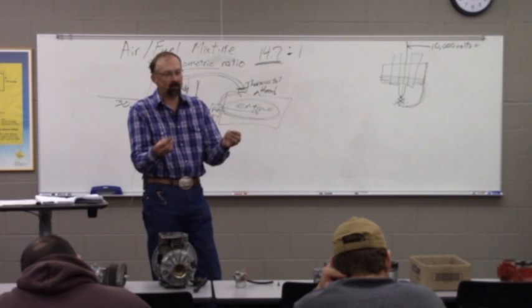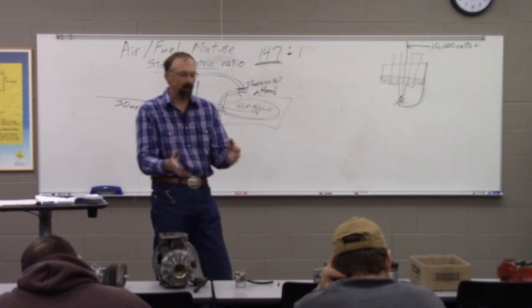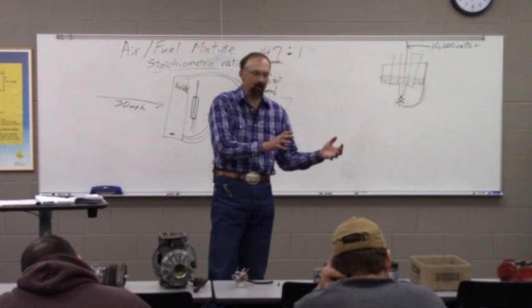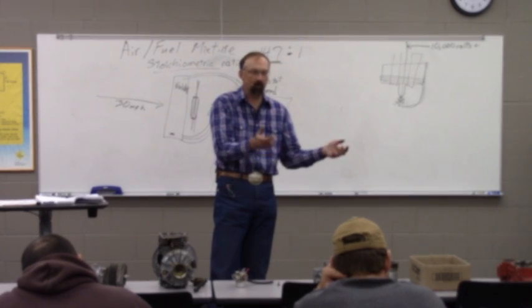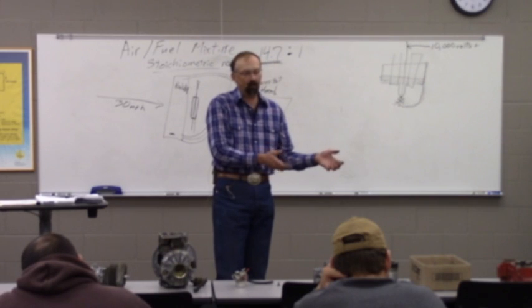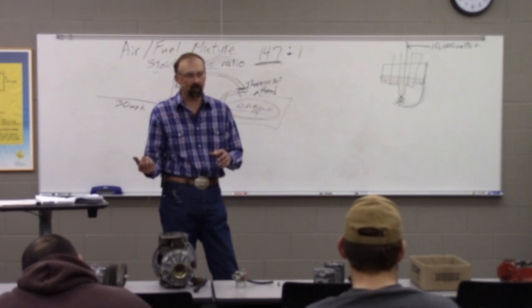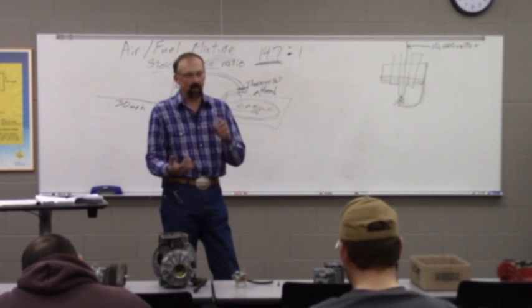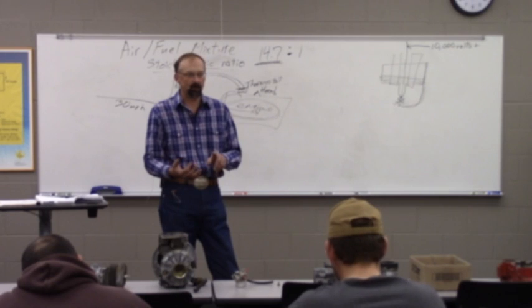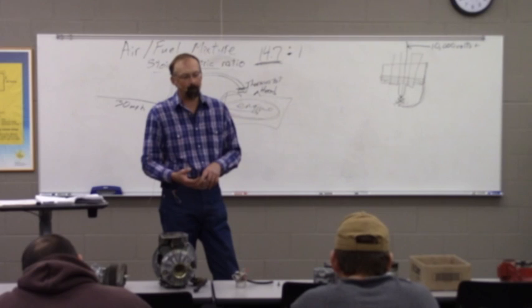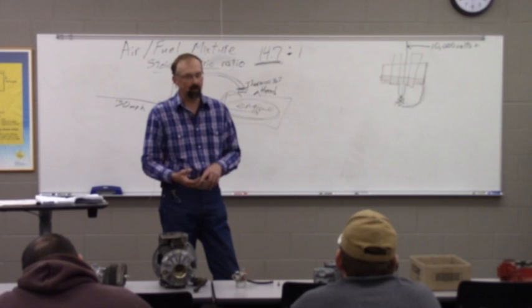So what we're actually seeing, in the old days, you were needing to change that oil in a lot of those because it had broken down and wasn't really lubricating well anymore. These days, rarely do we change it for that reason. We're usually changing it because of contamination. It's got too much soot or acid or water or other contaminants in it. But boy, we sure don't see it break down the way it used to.